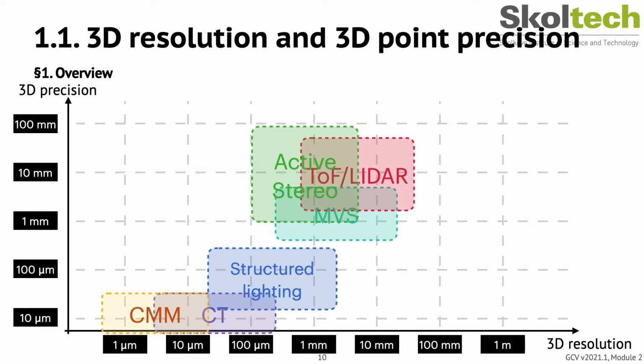Another question is, what is the typical resolution of depth measurements, and to what extent are those sensors accurate? In other words, what kind of geometric detail will we be able to reconstruct, and how precisely? Note that for most sensors, 3D precision, meaning the accuracy of individual 3D measurements, depends both on the range of scanning and the desired 3D resolution, that is, 3D precision is not constant.